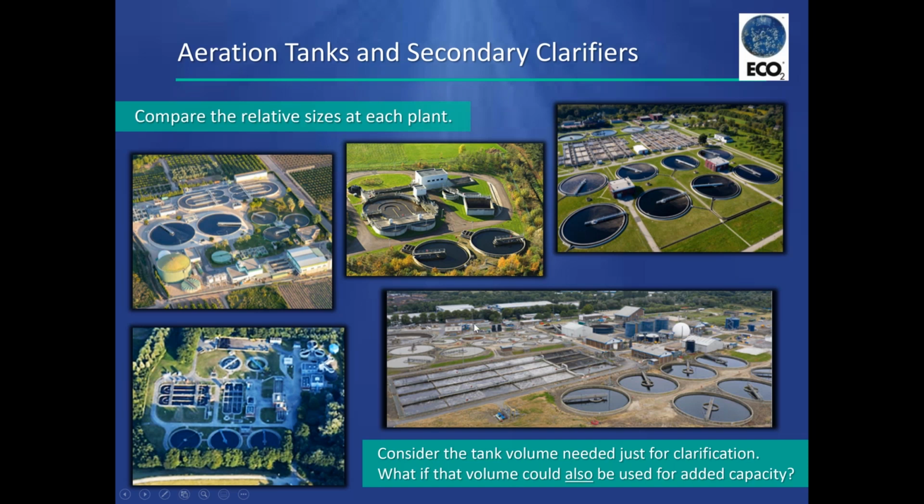And so, as I mentioned, the sizing is based upon the F/M, how many pounds of biomass do we have to maintain on the site to handle whatever pollution load comes in. So the aeration tank contains the necessary amount of biomass, and then that, of course, is the place where we transfer the oxygen.